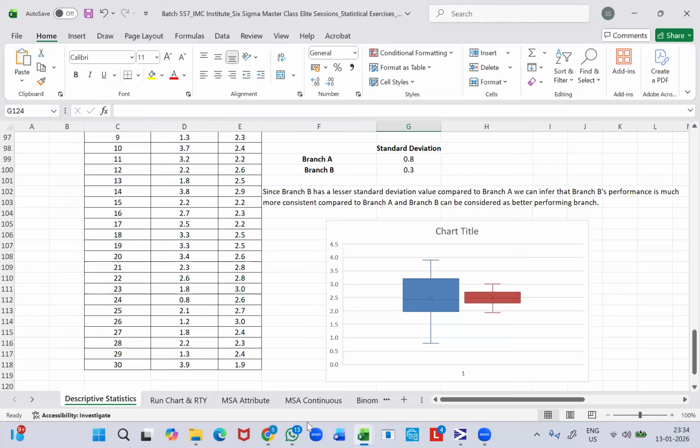And we also looked at an exercise and saw how to calculate the rolled throughput yield. If you want to apply the manual formula, as I told you, in the final assessment the question itself would provide the throughput yield values in terms of percentage. In order to calculate the rolled throughput yield, we need to convert these percentage values into decimals and then simply multiply them, irrespective of the number of sub-processes.